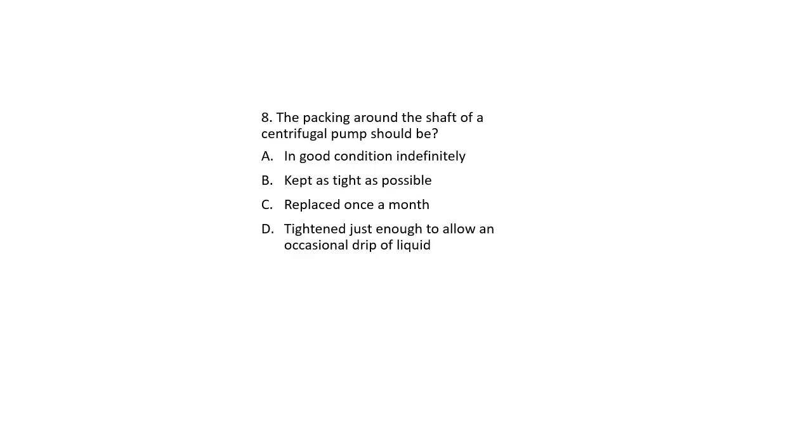Packing around the shaft of a centrifugal pump should be in good condition indefinitely, kept as tight as possible, replaced once a month, tightened just enough to allow occasional drip of liquid. Answer is D. Water leakage is used for cooling and lubrication.